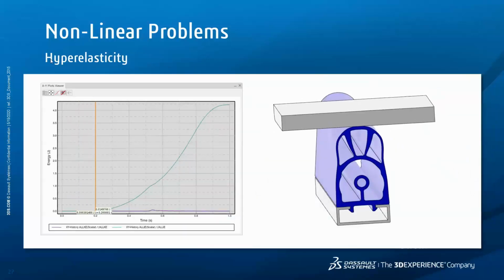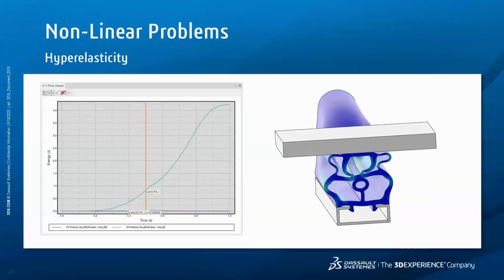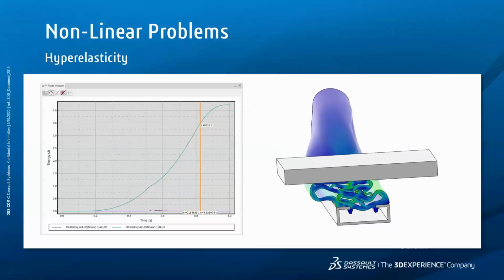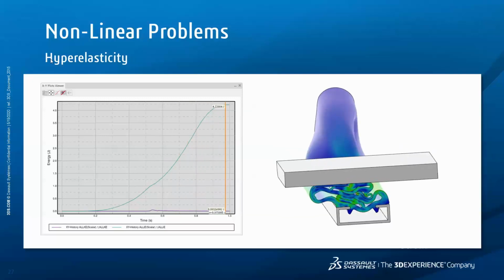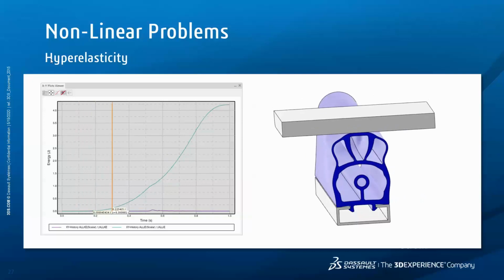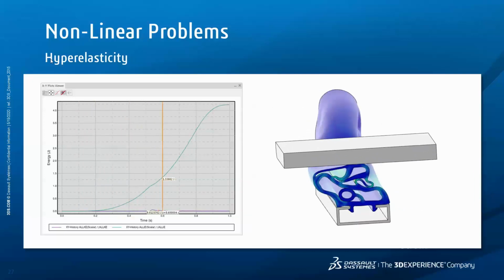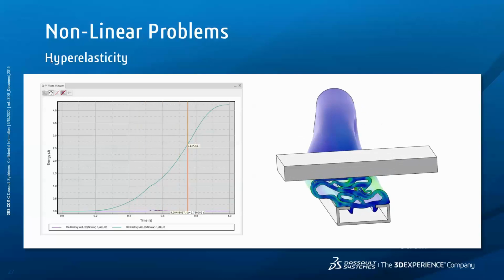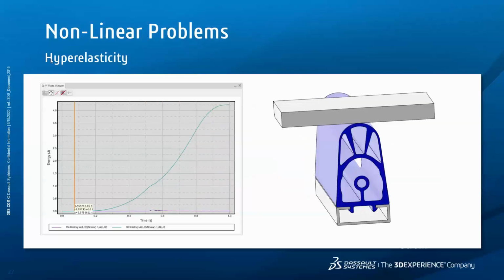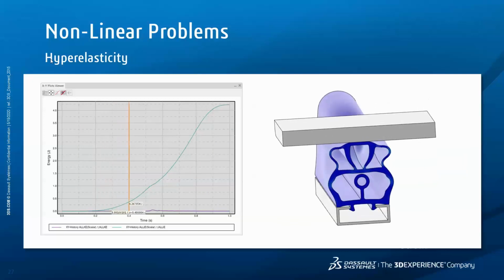We can also deal with non-metallic materials, such as composites, hyperelastics, viscoelastics, and hyperfoam, to name a few. For hyperelastics, we have a greater selection of material models to more accurately define your given product. These include the basic neo-Hookean approach, with further models available, such as Yeoh, Marlow, Ogden, Arruda-Boyce, and Mooney-Rivlin. Selecting the appropriate model from experimental data is made easier through use of the material calibration app packaged with Structural Mechanics Engineer.